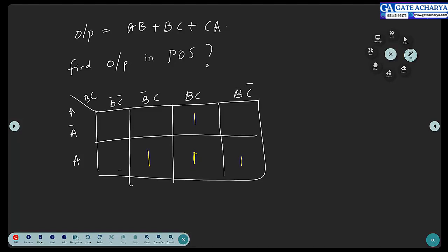One more thing. I'd like to add one more thing. The output positions of ones, or in other words min terms, is represented by the summation symbol. Where do I have ones? This is 3, 4, 5, 6, 7. So 3, 5, 6, 7.